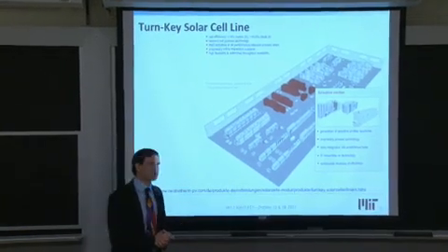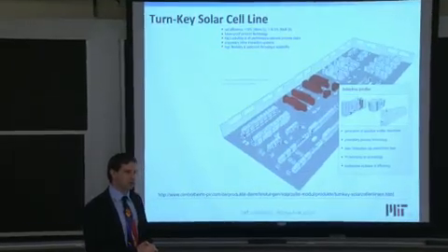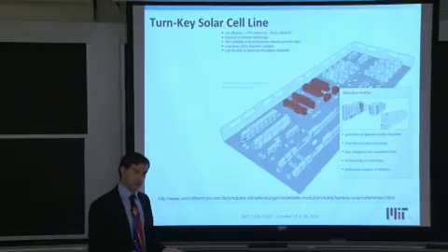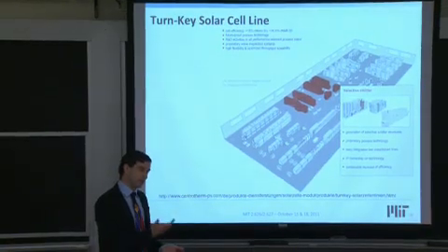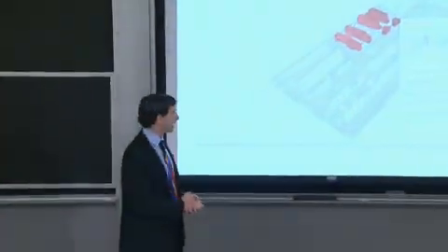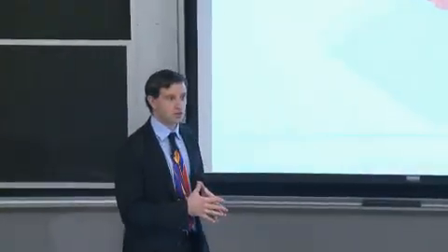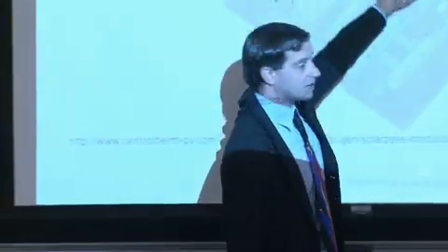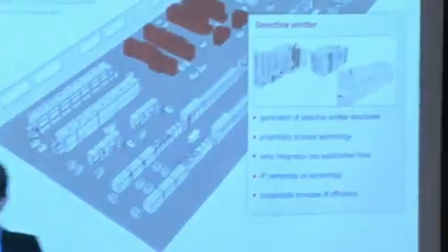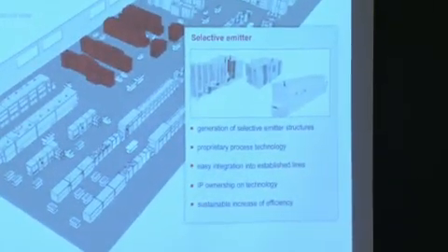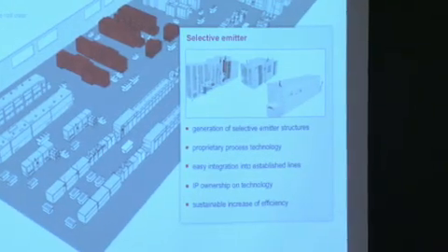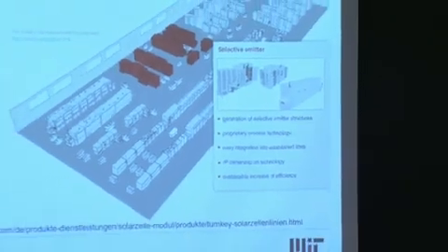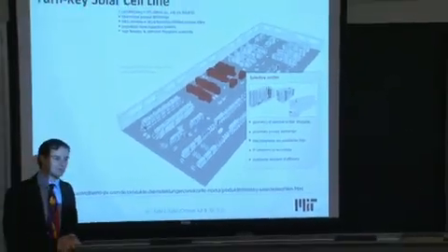One of which involves creation of porous silicon on certain regions of the wafer that you want to etch back and create the shallower emitter, leaving the deeper region intact. In that, you could use a form of shading. You could use a wax even for it. There are a variety of technology options for achieving that goal. But in a sense, many of the selective emitter designs involve a deep diffusion first and then a partial etch back. For example, creation of porous silicon and then etching that material away.